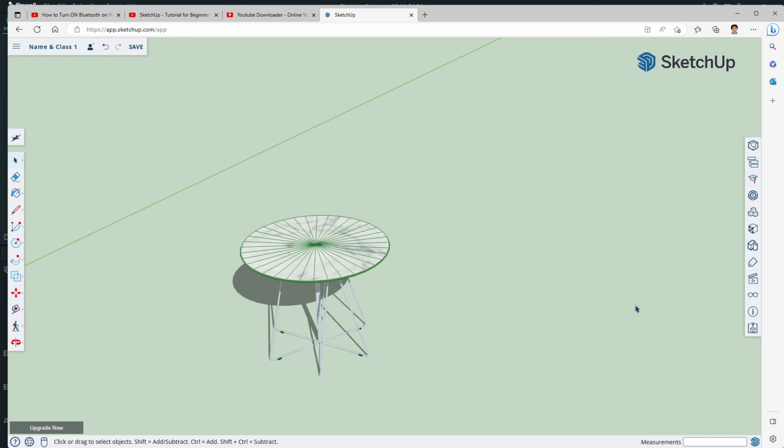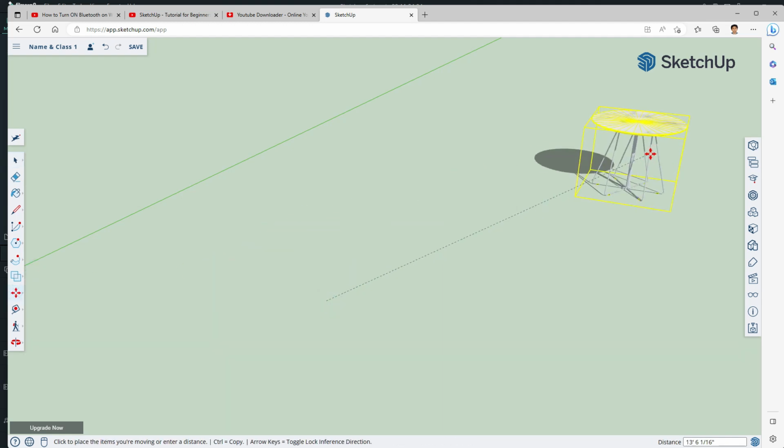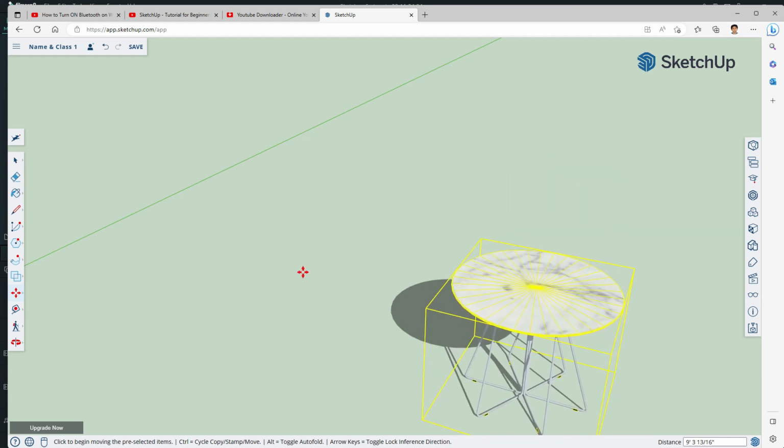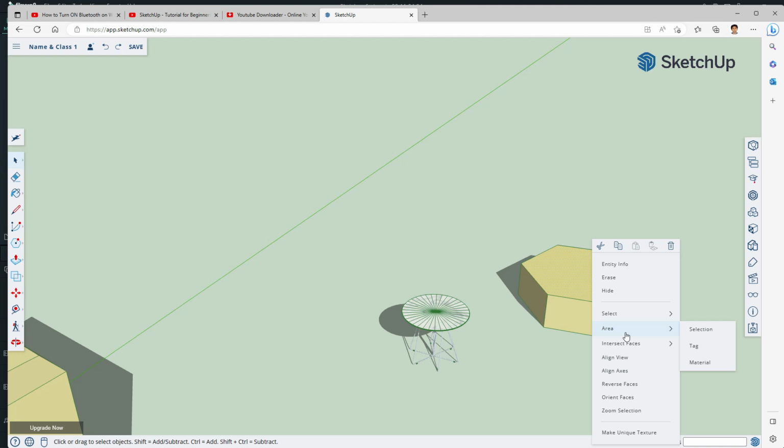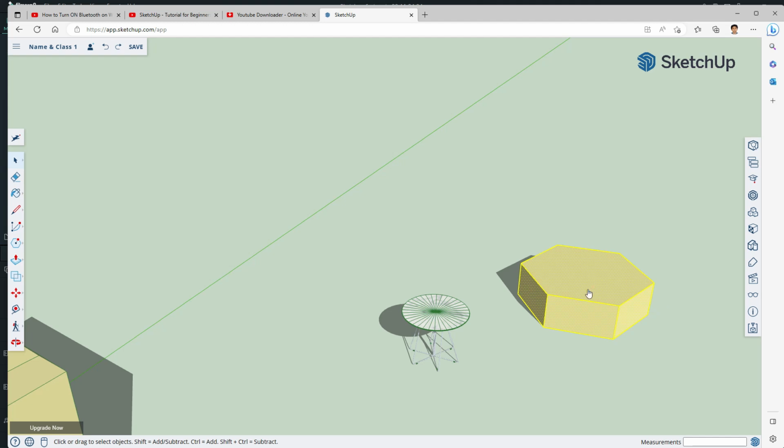You can change it to select the whole item. You will select the whole item, then you can move with the move tool where you want to keep it. If you want to make a group, suppose these lines, and you want to make one group for this, and everything will be joined as one item, you have to right click. First select this item and then make group. So you can see now this is one group. Now if you move this, it will move as a group.